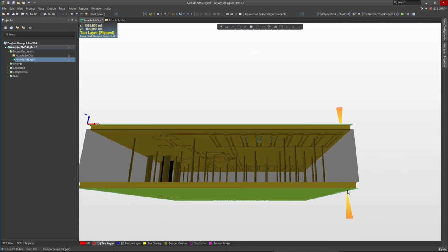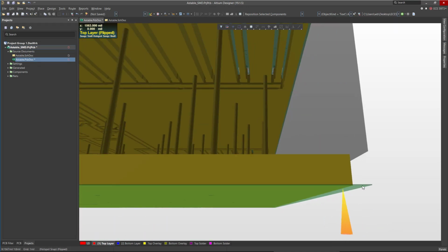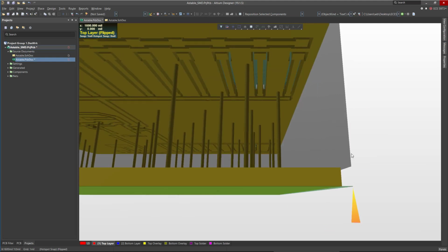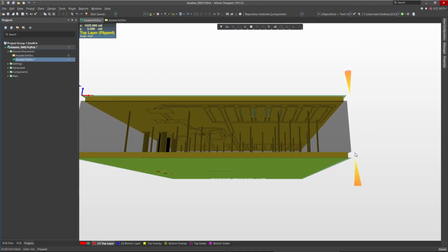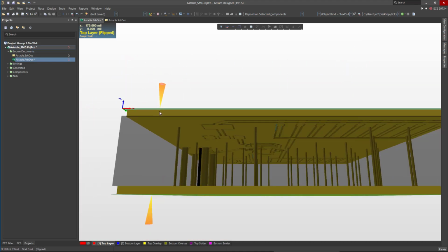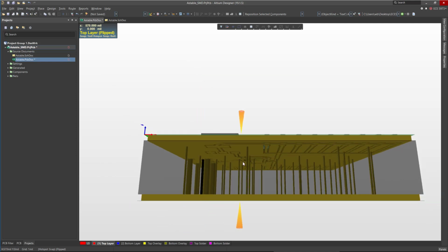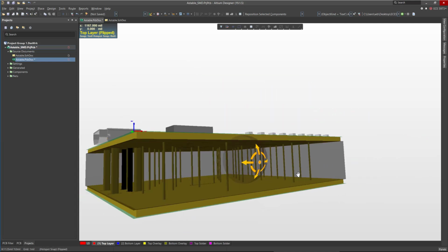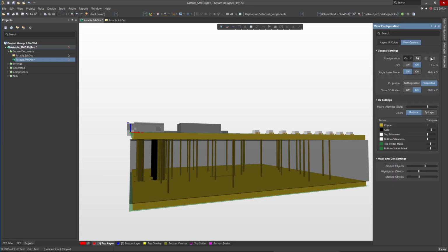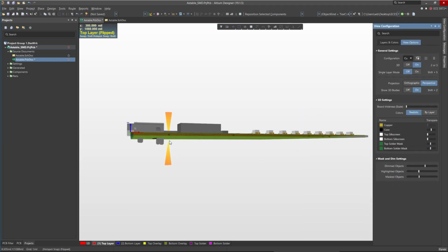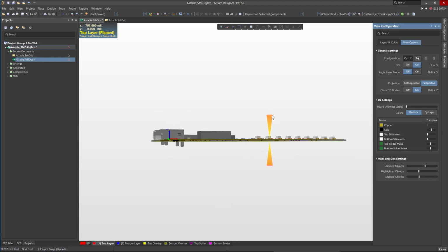And this green one is basically the solder mask. And this gray one in here is the core of the board. This one in gray is basically the laminate material. And this is the 1 ounce copper, and this is a 1 ounce copper as well on the top and bottom. So now they are scaled, they are spaced actually. So if you go back to the original scale, now the thickness is 1.6 millimeter.